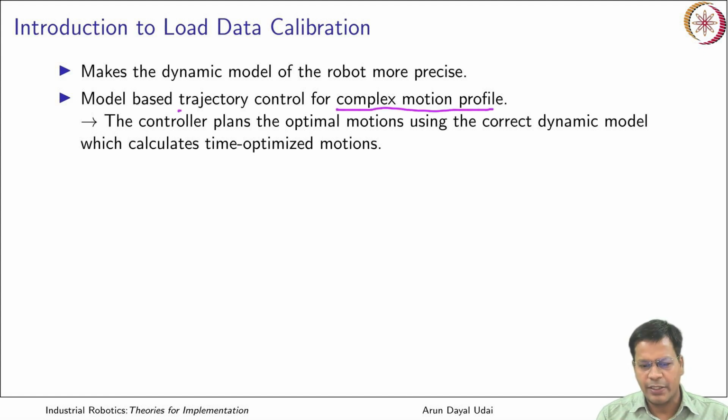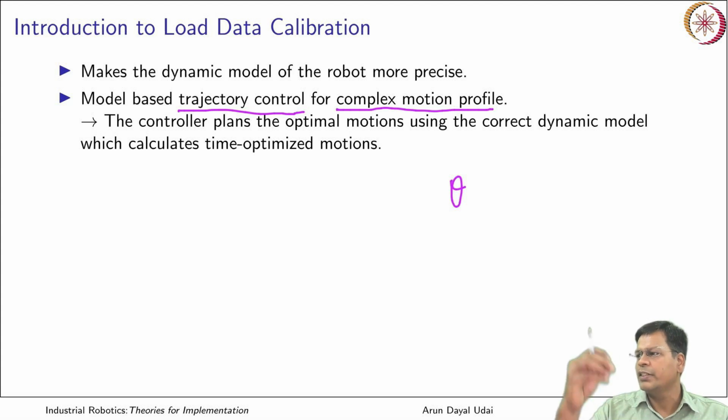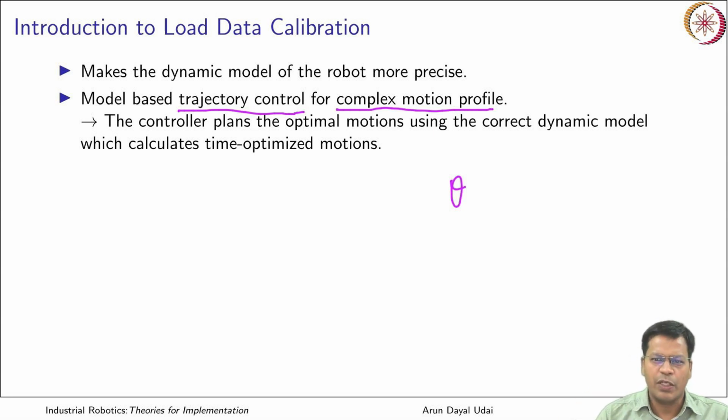Okay, and trajectories are there. It is not just the path which is important, it is the trajectory also which is important. That means at each and every point you have a fixed set of joint angles and the Cartesian values of its end effector. Those points are not just freely stated in space, they are to be there in a manner where time is also varying, right? Each and every point is defined with respect to time. That is why your acceleration profile is important, your velocity profile is important. So everything becomes very critical when a trajectory is there.